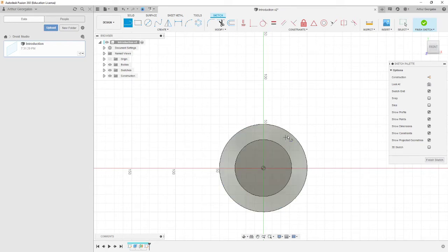Like right now, I want to draw my line starting from this edge of the circle, but it doesn't, because for some reason, however Autodesk decided they wanted it, you have to select the object and project the geometry to it. You can't really reference bodies very well. You have to have it as a sketch, at least to make things consistent.